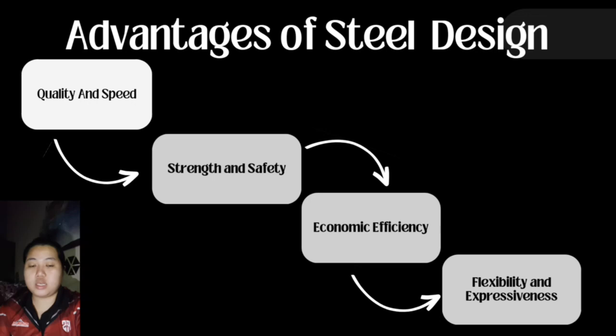A steel structure is 30 to 60% lighter than a similar one made from concrete. As a result, the load on the foundation is considered lower. Constructing a building using a steel-based structure requires less material for its foundation than the same building would require if it were made of concrete.